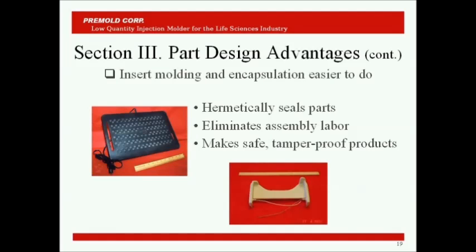You do have to consider the size and stiffness of the insert because the resin wants to shrink a little bit, and the insert doesn't want to shrink. But again, a RIM molding engineer can help you with those considerations.